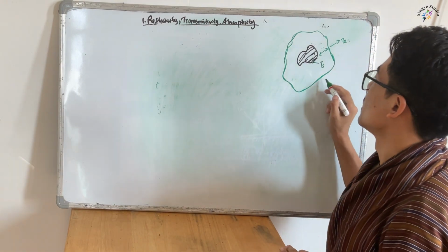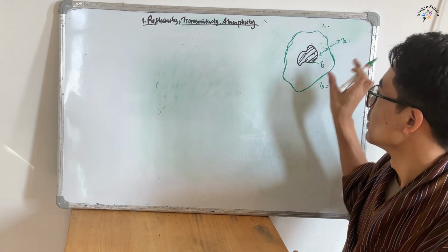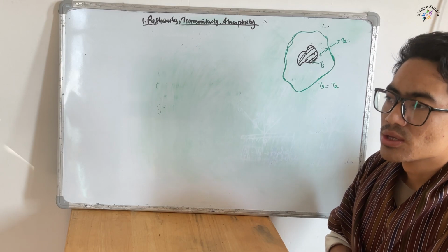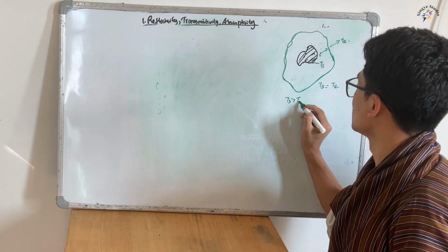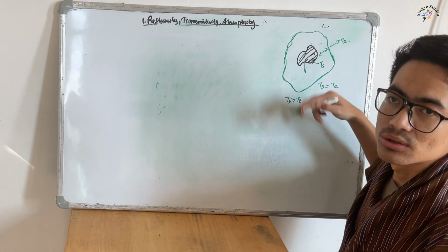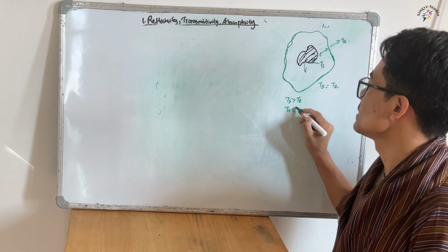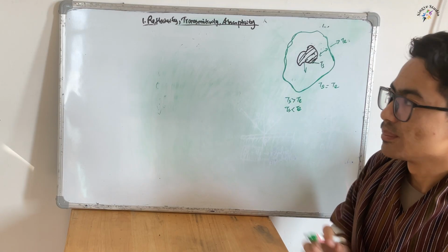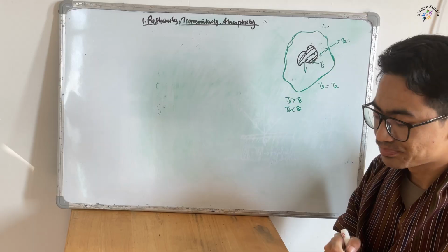So what do you say when I say Ts equals Te, which means both bodies are in thermal equilibrium. Okay? So in the previous class we learned that if Ts is greater than Te, what happens? The body begins to emit radiation towards the boundary or the environment. If Ts is less than Te, then the boundary will emit radiation to the body, right? Because the heat transfer due to radiation is by virtue of its temperature.